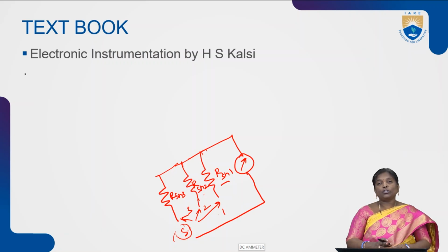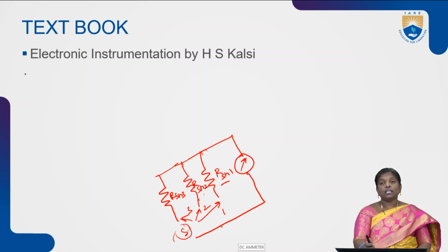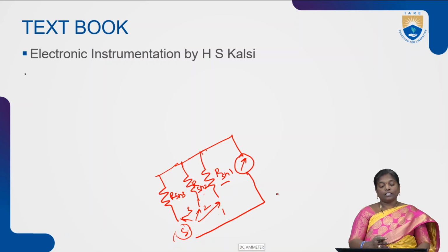To overcome these two problems, before removing the connection across the first resistance, we make the connection across the second resistance and then remove the connection from the first resistance. Then according to our requirement, we can measure the current readings.